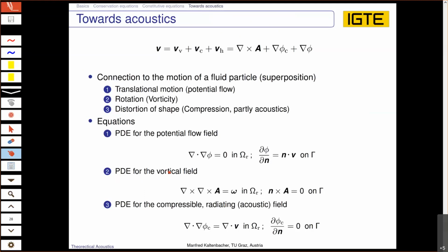For this, it means we have to describe the flow up to some limit correctly, and on the other hand, get the idea how we can model the acoustic sources being generated by the flow, and then take these sources for a separate computation, in most cases on quite a large domain, but there we just solve for the wave propagation.